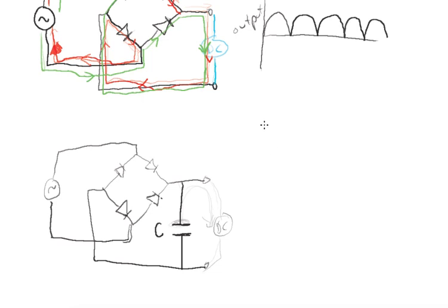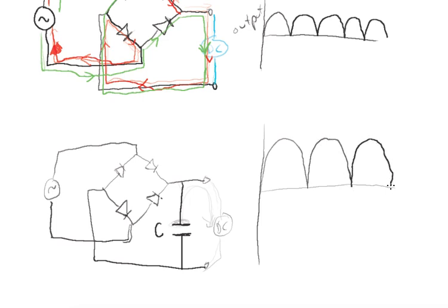And so what happens is, and I'm going to draw this a little bigger, we'll learn about how capacitors discharge, but we take something that looks like this, this full wave rectified thing. And what happens is when we get to this point and the current starts to go to zero, the capacitor starts kicking in and it discharges slowly, and it does something like that. And so instead of going down to zero, your current comes up like this and then cuts over, and you eliminate this part where it drops to zero.